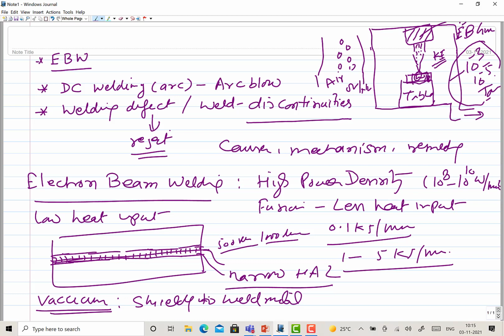In case of machining, we basically carry out the sublimation or evaporation of the metal, so metal is directly converted into vapors. There is no melting as such, because of the high power density that is realized when using this electron beam. It helps to evaporate, so the controlled removal of the metal from the workpiece leads to the machining.